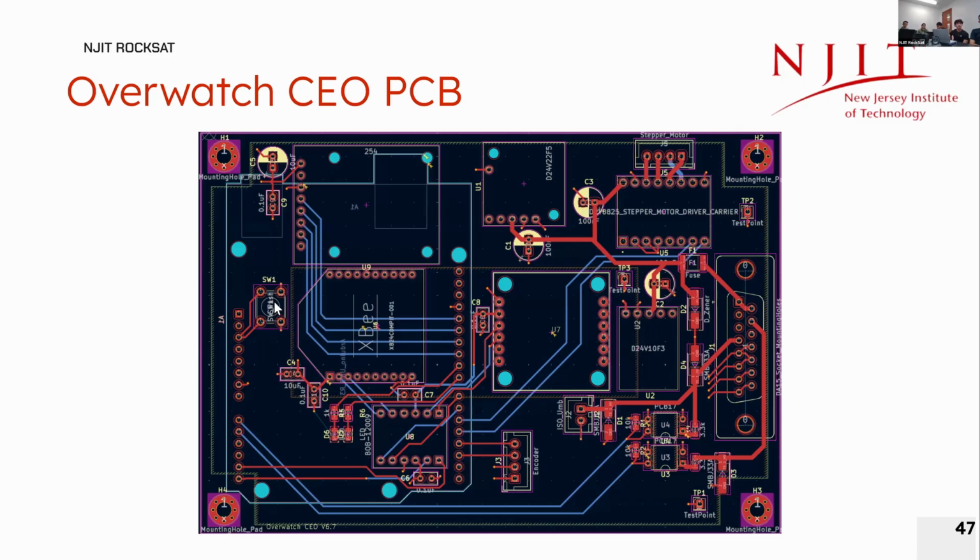The main reason for the added reset button is because the Arduino will be shielded and it's on the opposite side to maximize the space usage for the modules. And the reset button will allow us to access the reset, of course. And as you can see, the thicker traces here indicate the 28-volt power line. And you can see the 3.3-volt island here and the 5-volt around, and the little moat designed around the optocouplers to isolate the noise within as it receives a signal from the connector.